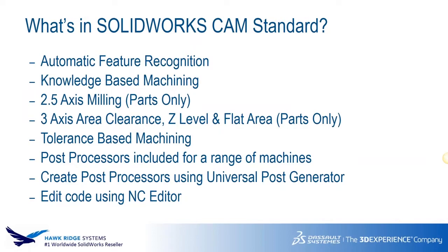It also includes tolerance-based machining. So that's going back to the model-based definition information that I just talked about. What that essentially does is it will look at the types of features that it finds, but it will also look at the tolerances applied using the MBD information and extract the tolerances and use those tolerances determining a machining